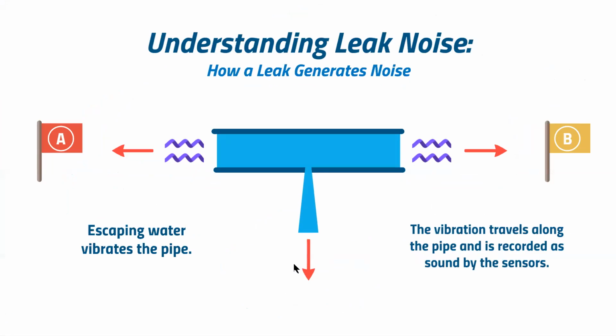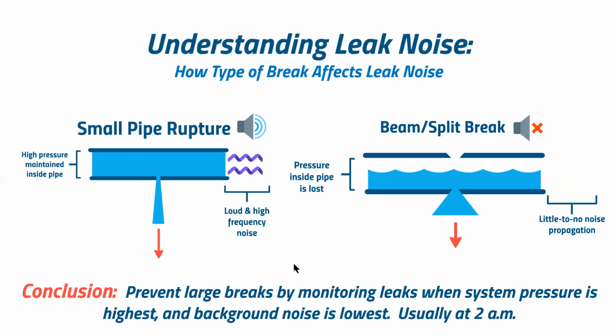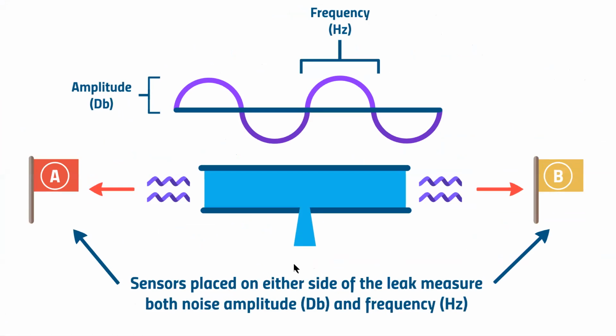Yes. When you have your sensors on pipe, there is a possibility that your pipe will change material in between your sensors, and that does indeed play into the accuracy of your leak location. Your leak detection software, whether it be the ZoneScan Net or your 610 processor, allows you to put in multiple segments of pipe in between your sensors. So inputting the correct material and diameter as it changes between sensors will allow the software program to recalculate the math to still accurately pinpoint the location of the leak.